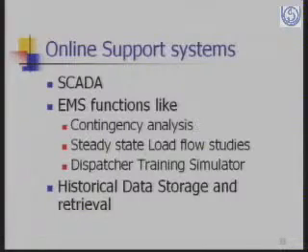We also have EMS functions at the regional load dispatch center, which means energy management systems, like software for contingency analysis, steady state load flow studies, and dispatcher training simulator. We also have systems for historical data storage and retrieval at these regional load dispatch centers to help the operator decide what has happened in the past and how he can deal with the emergency which is arising.